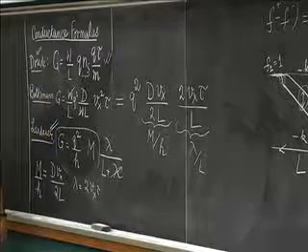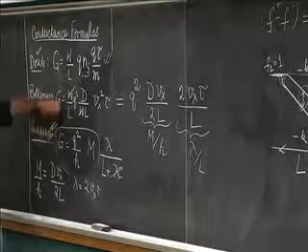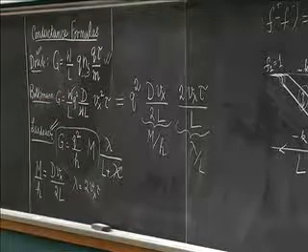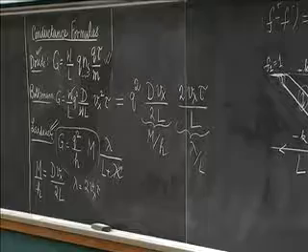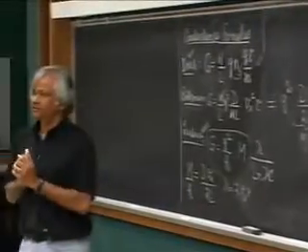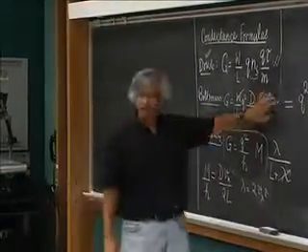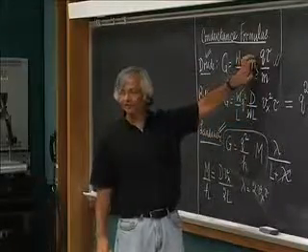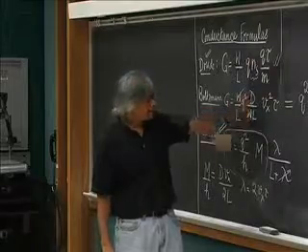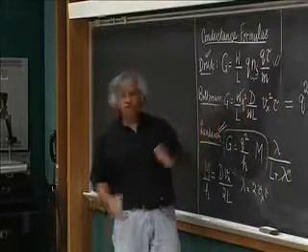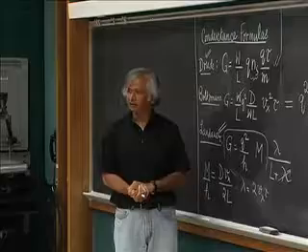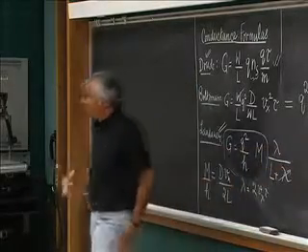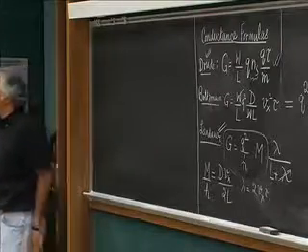That's it. The advantage, of course, is that this one is relatively harder to derive. So you have to go into the Boltzmann equation, and it takes a while to understand the Boltzmann equation, and then there's various approximations that go in before you get here. So it's a lot harder to derive, which is why the expression you usually carry in your head is more this one, not this one. Okay? And the other thing is, this only applies when you have a very long diffusive conductor. Whereas this way, you see, you have something that interpolates nicely between the ballistic and the diffusive regime. Just goes continuously.